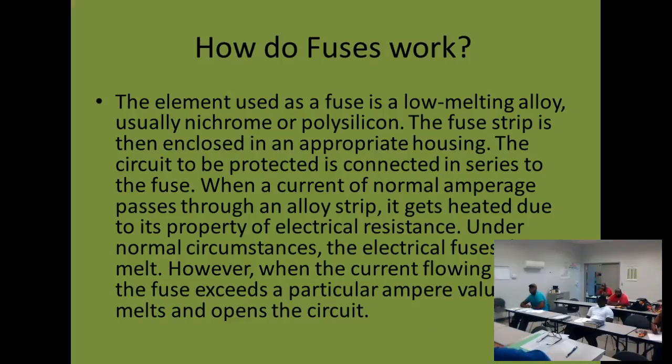Your meter cannot tell you that. It can tell you that there's no voltage difference, okay? So always keep that in mind when you're starting to put your hands in there. Do I know how to read my voltmeter?